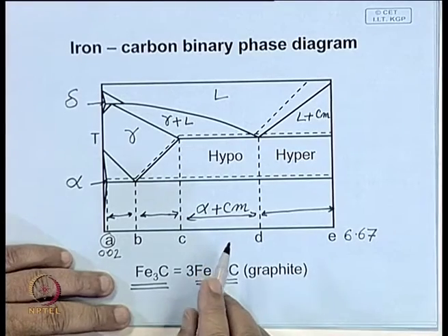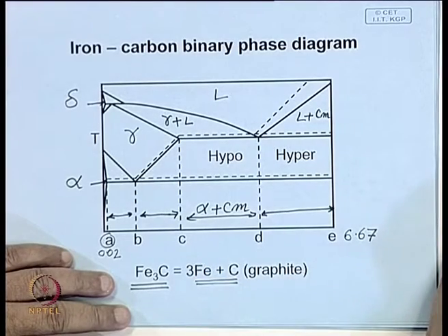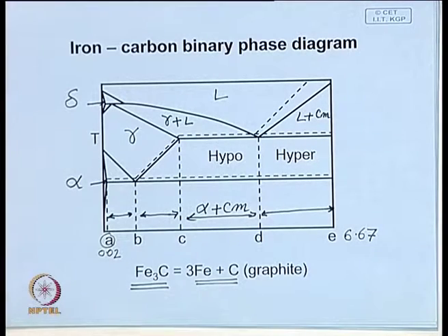In fact, in many of these materials, particularly steels used in power plants and petrochemical industries, where the steel is exposed to higher temperature during service, people have looked at the microstructures after 20-25 years of service and found that cementite has broken down into ferrite and graphite.